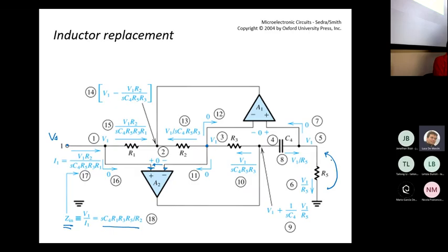So when you have the information concerning the voltage applied to the resistor, you can compute the current by virtue of the Ohm law. And this very current is the same current which flows through C4, because there is no alternative path. No current can flow here. So V1 over R5 is the same current which flows here.